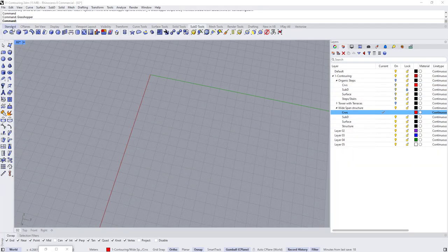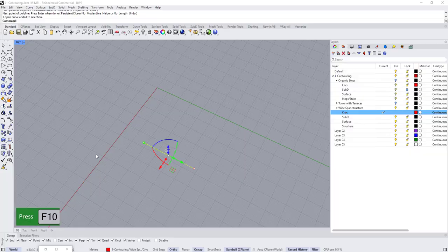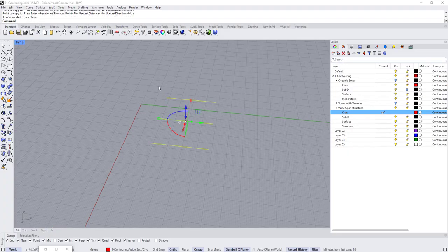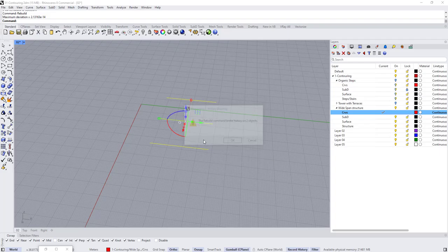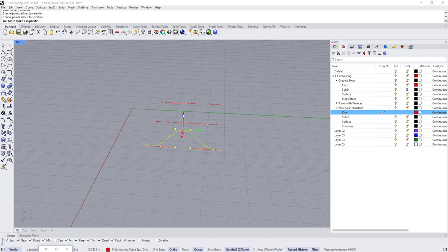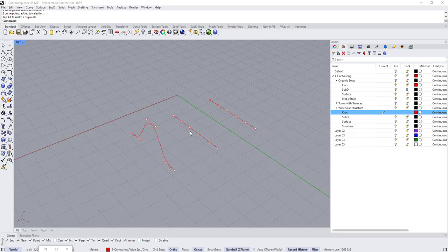So I'm going to select the curves. Let's come here and draw maybe a curve here, make it 40 meters. So the span is going to be 40 meters. Click and let's create a copy. Maybe copy here 30 and copy after 60 meters. Select everything, rebuild. Let's set control points to 10. Make it sub-D. It's okay. Press F10 and let's start maybe moving the points. Move this up, maybe something like this. And maybe this one, move it vertically by a value of maybe 6 meters.